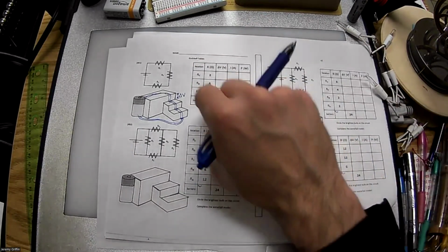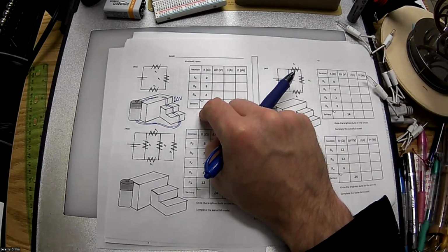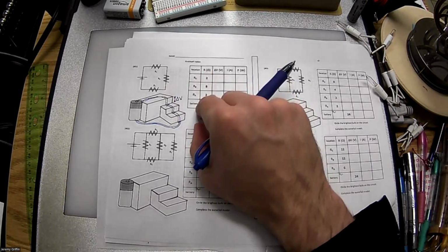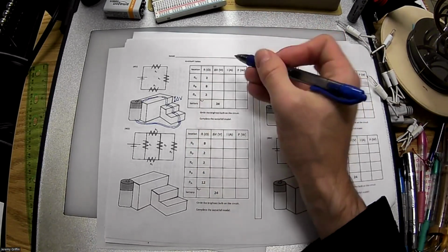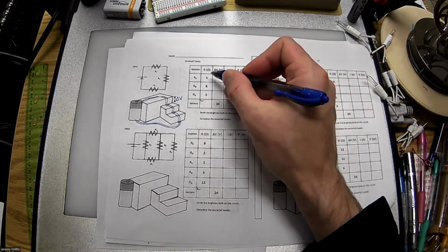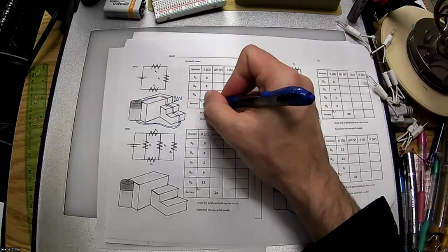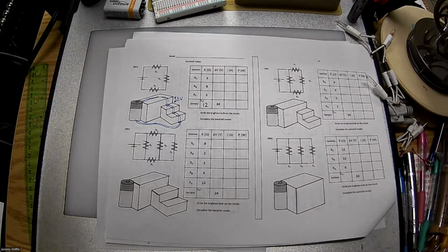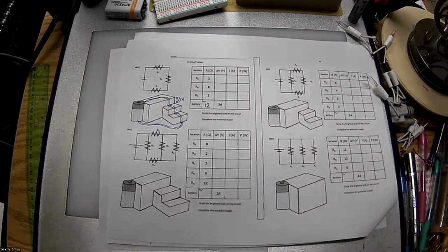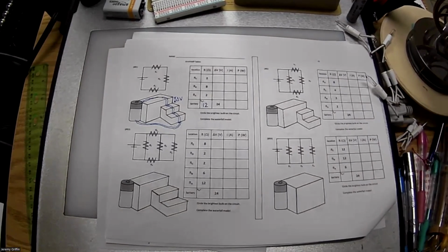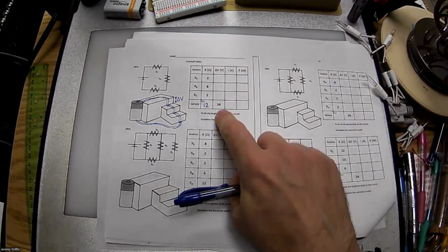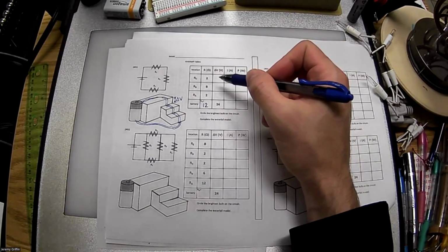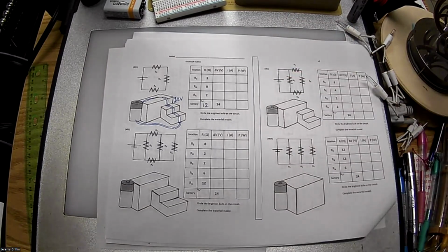Like that. What is the equivalent resistance for the entire circuit? Well, since it's just 3 in series, what do you do with these numbers? Add them up. So in my case, 2 plus 8 plus 2, it's like 10, 11, 12. It's like 12 ohms resistance I have, 12 ohms. Everybody good so far? Then I gave you the battery, how many volts that is. Next column, what is the voltage drop across each individual resistor?